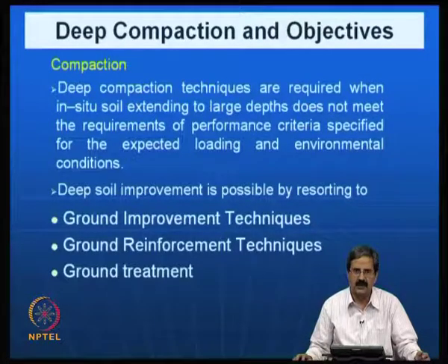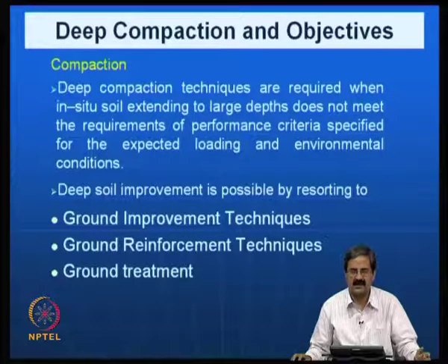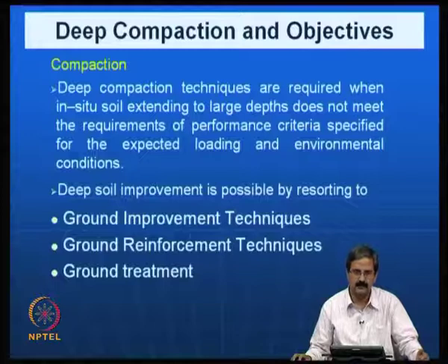So, by using some deep compaction techniques which we would be discussing, we try to stabilize the in situ soil which is, for example, about maybe 10 to 20 meters below the ground level, as opposed to shallow compaction where you just compact the soil to about half a meter to 30 centimeters in different layers.